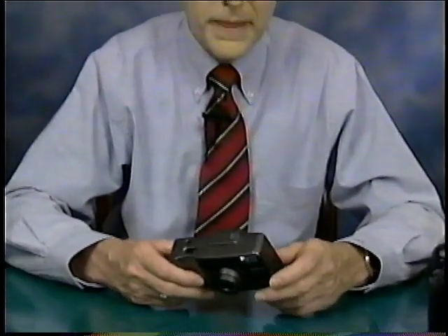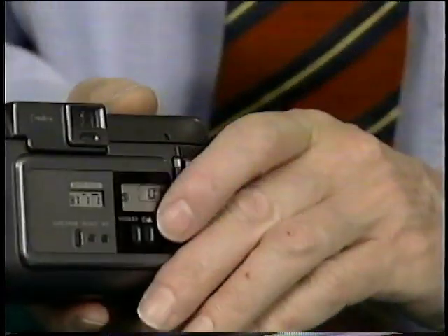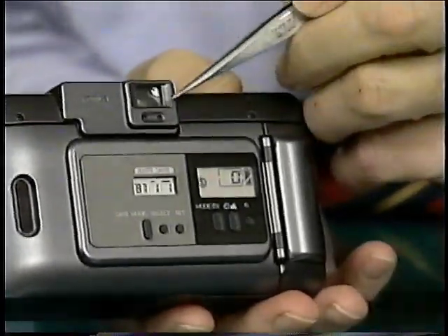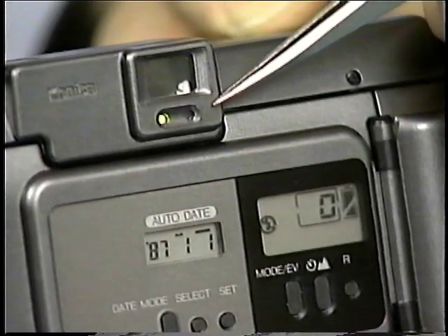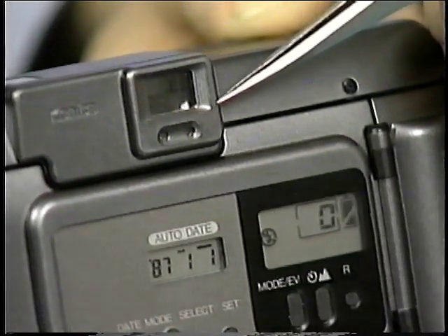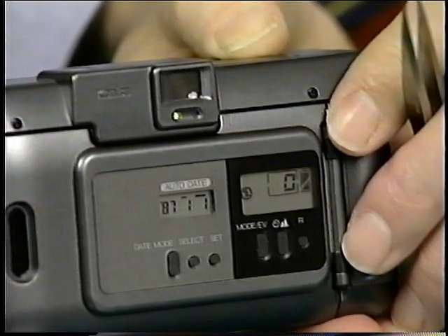There are two tests you should make on lens shutter camera autofocus systems. One is to see how it's ranging or if it's finding the right range, and the second is if the lens is actually focusing. And both those you can do visually and very quickly. Most of the newer type lens shutter cameras have LEDs near the viewfinder window. You can see this one. And if I press the release button a half stroke, you'll see that the green LED is lighting in a steady fashion. This is with the release button pressed 1/2 stroke, not a full release stroke, but just 1/2 stroke.